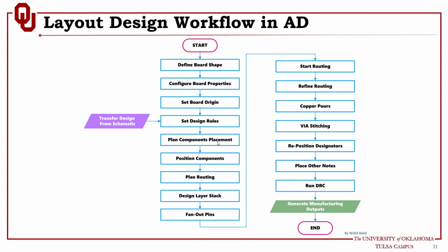If you are designing a board with a microprocessor, FPGA or microcontroller, these are the core components, because they branch everywhere to all the surrounding peripherals or components. So start with this component, place it in the center of the board, and see how you can distribute the rest of the components. You don't have to keep it in the center, but this is your core component where everything will branch to. So start with it.